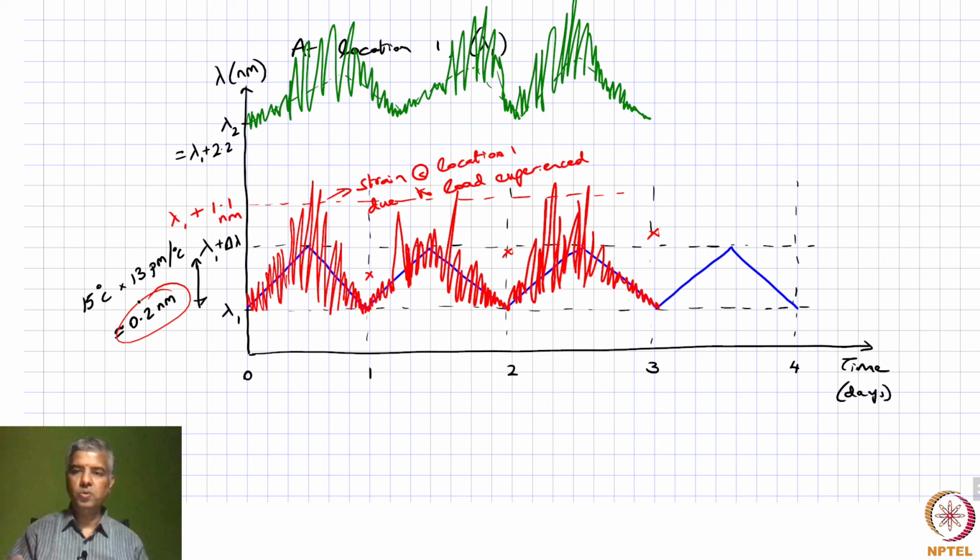But if you have an industrial process where the temperature that you see at lambda 1 can be very different from the temperature that you see at lambda 2, and so on, in those cases you want to make sure that you account for that, and correspondingly design your next lambda to be at a slightly longer wavelength.